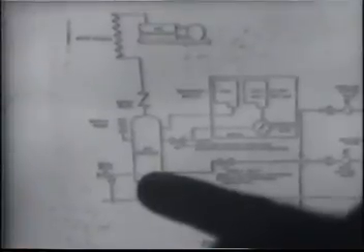So we compress the air, we store it in a tank. This means that we have some stored energy there, sufficient for about 5 operations with no more source of power there. If we lost our AC supply to the air compressor, we still have the possibility for 5 closing operations. Remember, we can always trip the circuit breaker. And in connection with the air compressor system, we have the governor switches, low pressure alarms and different supply valves to operate the air system.